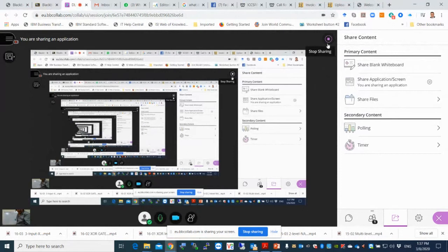After this identification, I have to do what? Have a block diagram in step number 1. Step 2 is the truth table. Step 3 is the K-map. 4, equations from the K-map. 5, circuit diagram. Okay? Make sense? Okay. Let's go back here.